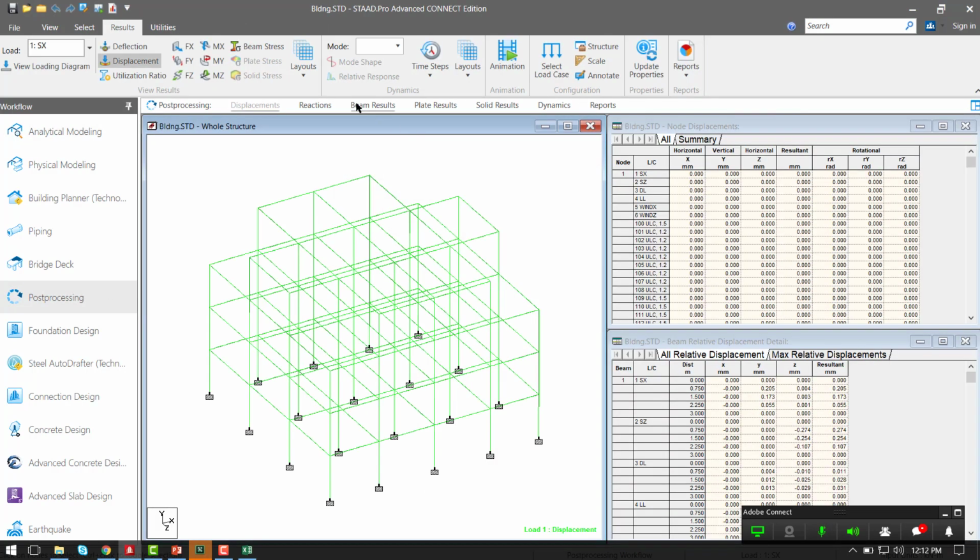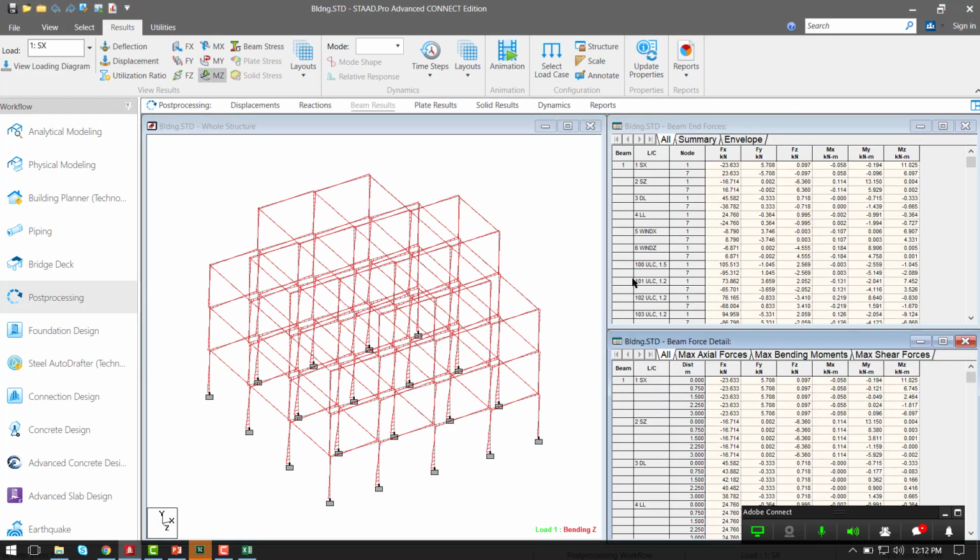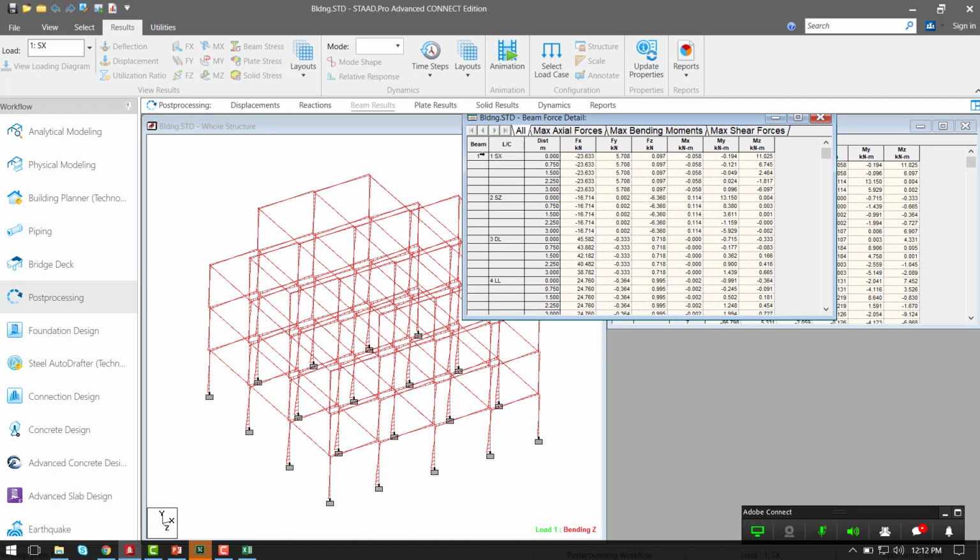If you go to the post processing file, you can find that the section forces are reported for 5 sections, so start and end and intermediate 3 sections. But you need the section forces for 12 sections to design any member. For example, like a deep beam, we do not perform the design of a deep beam. You need the 12 sectional force values for this particular member.